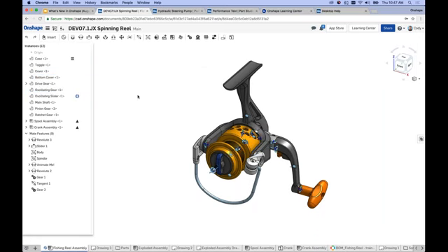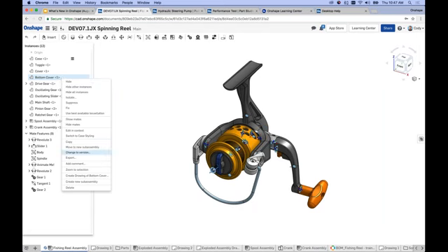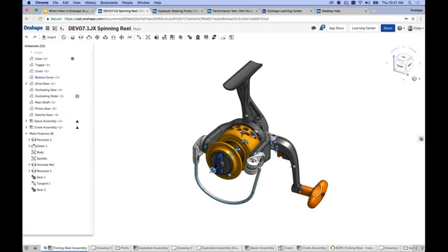But the big thing I would stress is, again, just keep in mind that you can choose the change to version at the assembly level, or you can right click a drawing tab, say change to version, and it will allow you to do that, right? The thing that I would stress is new, is the ability to reference the revision as an object. In the past, we could reference the version, but not the revision, right? So again, especially useful if you like to create drawings of released parts that have established revisions. Depends a lot on the workflow.